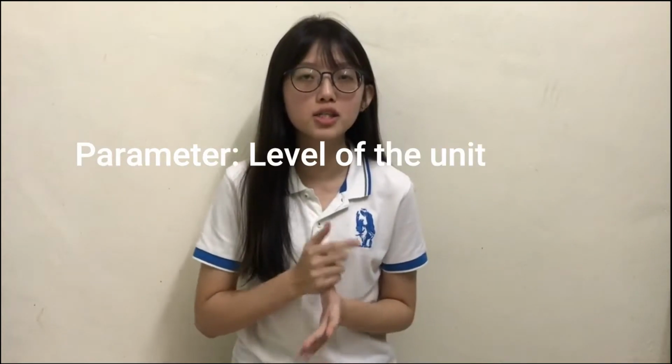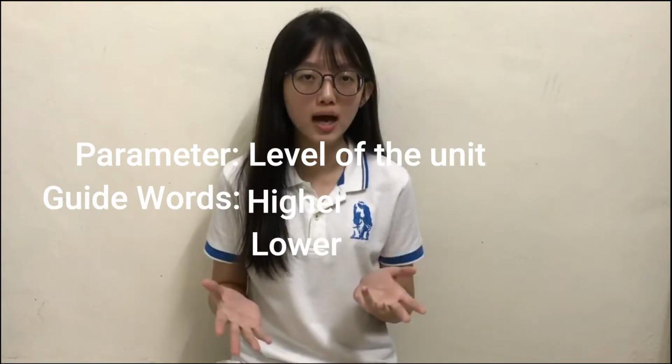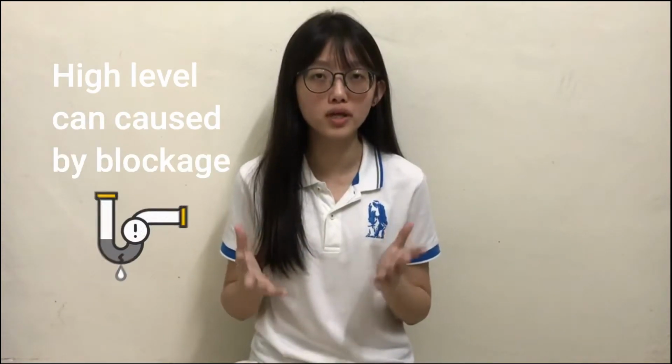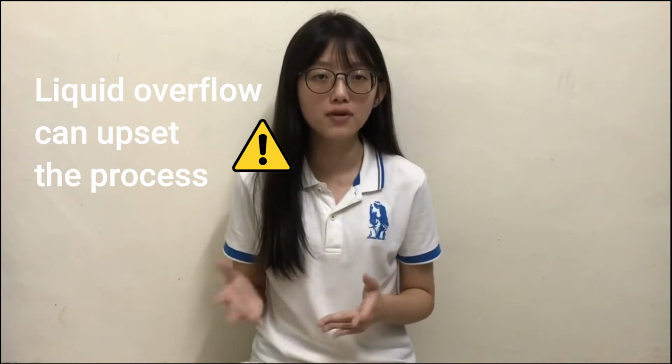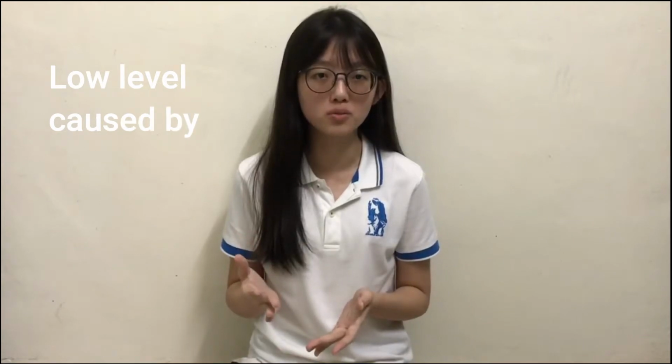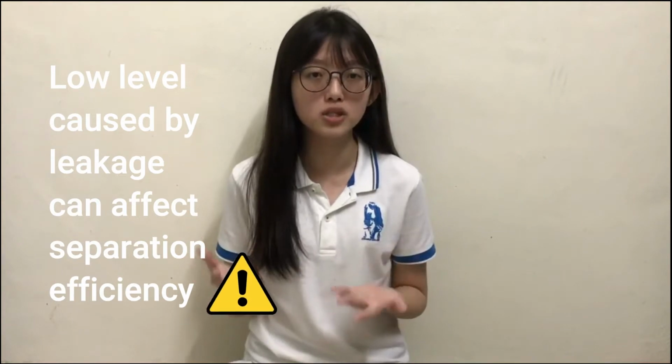For the absorber unit itself, as the study note, a parameter such as level is studied. The guide words for level are higher and lower, which means the deviations are higher level and lower level in the absorber. High level in the absorber can be mainly caused by a blockage in the lean water stream or high flow in the solvent stream. This can lead to liquid overflow and will upset the process. A high level alarm is required in the absorber in this case. Next, low level in the absorber is usually caused by leakage in the solvent stream. This will affect the separation efficiency, which means the operating condition is not optimal. In this case, a low level alarm is required.